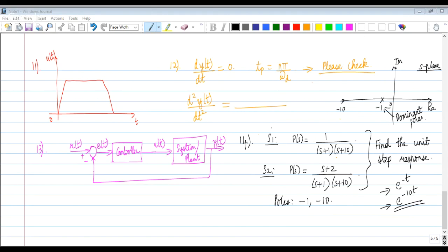So we typically use step response and frequency response. Please note that we are not only using step response. In this course, we also looked at frequency response, right? Those are two classes of inputs which are very useful for characterizing the class of systems that we are studying. Another perspective is that if you want to define parameters to quantify the performance of a system, you should always give the same input to the system. You should make sure that the input to systems is standard. That is why we use the unit step as a standard input provided to the system, and we analyze the corresponding output.